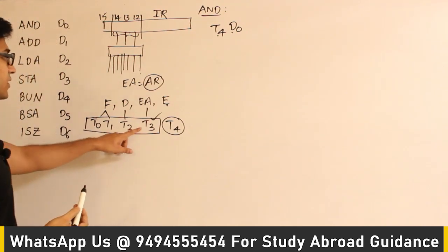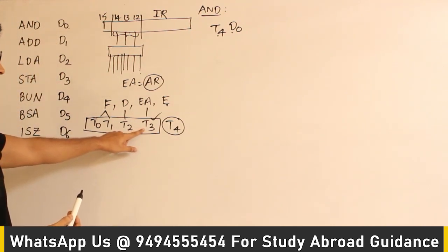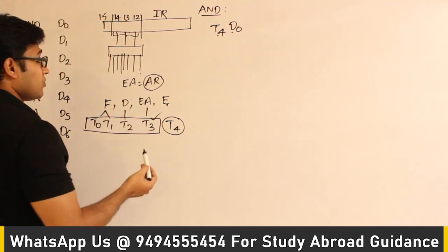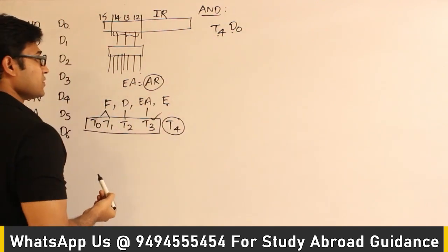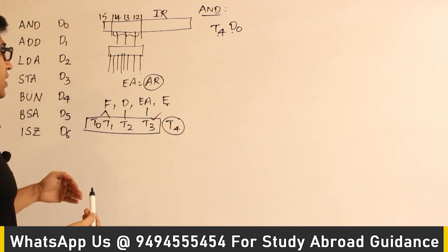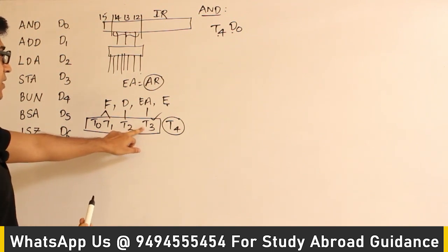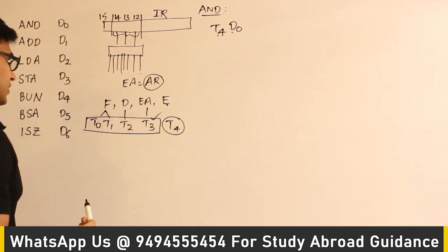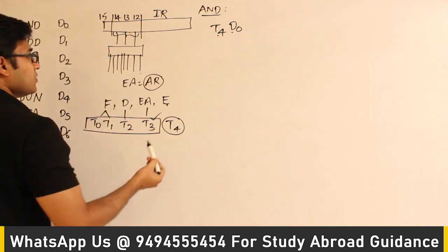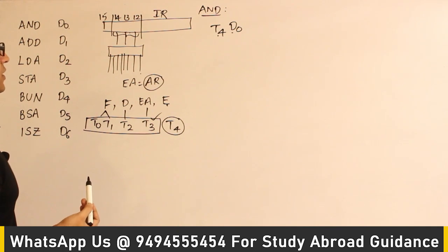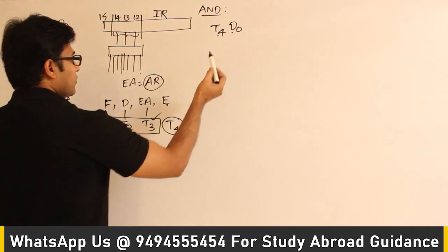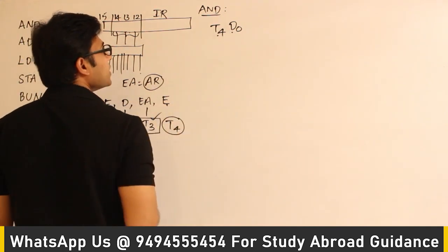In case you start executing the direct instruction at T3 itself, then we have to even check if it is direct or indirect. Depending on that, we have to take the actions. But just to avoid that overhead, we have left the direct addressing mode blank in the T3 timing signal. Therefore, in executing this, there is no need to check the I bit at all. Got it?